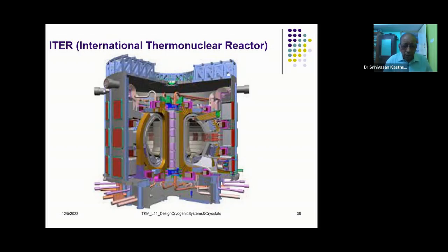Basically, it has superconducting magnets. The superconducting magnets are D-shaped, forming what are called the toroidal coils. These are toroidal coils. There are also poloidal coils mounted on the top zone, the mid zone and the bottom zone. These are the poloidal coils. For example, I think this represents a poloidal coil.